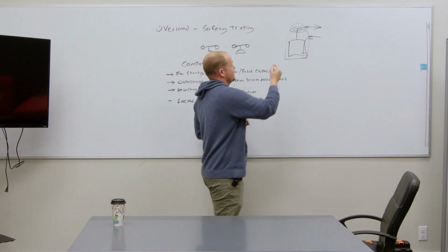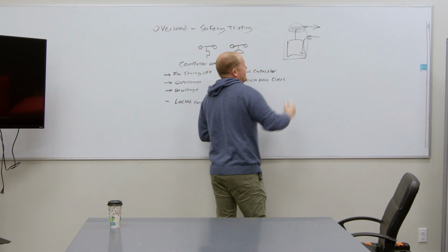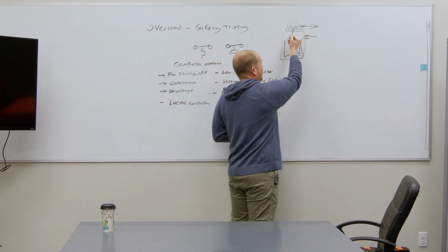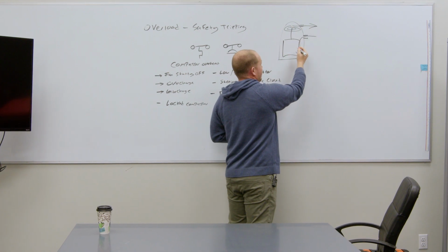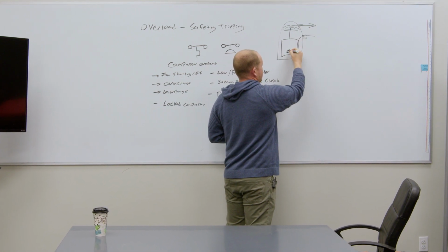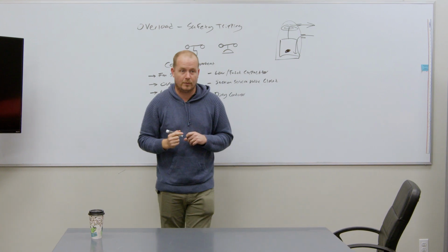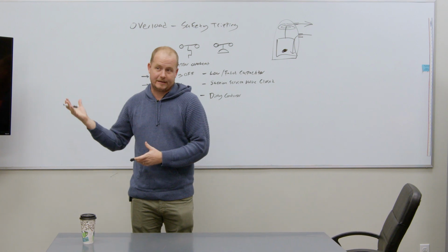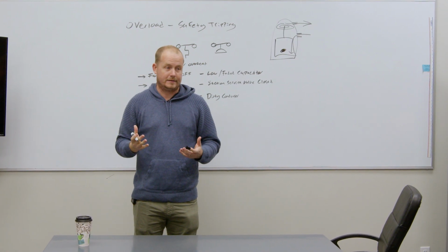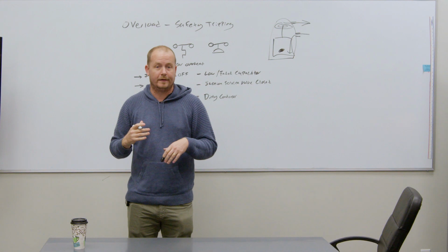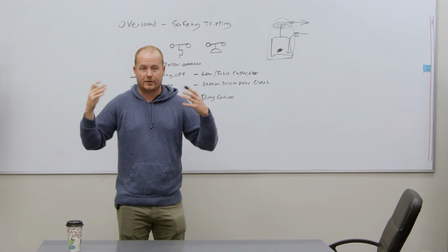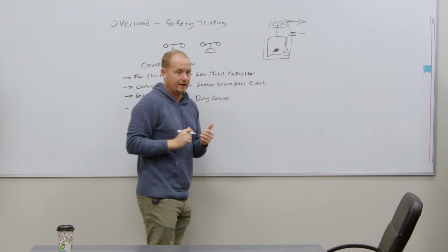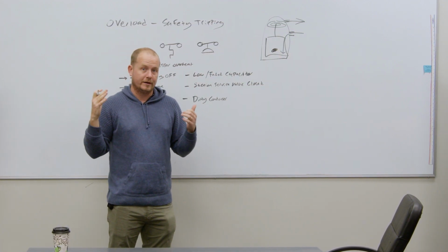If there's a mechanical issue way up here, and the heat is happening up in the top of the compressor, it's going to require that it heats up the whole compressor before it gets down to where the thermal overload is, somewhere in this area, behind the compressor terminals and the windings. So when you have a mechanical problem, even a failed condenser fan motor or a compressor that's got something going on in the head, or maybe it's high head pressure, dirty condenser, any of those types of issues, the entire compressor is going to have to get hot, the shell, the whole thing, before it trips that thermal overload.